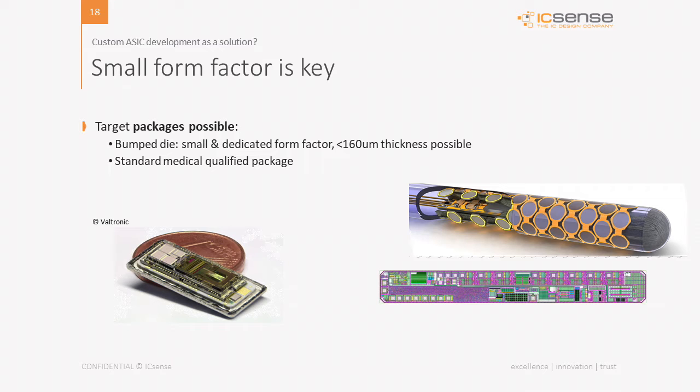On the other hand, we also see a lot of medical companies choosing standard medical qualified packages, such as a QFN and so on. The main reason is that in this case, you can use the same package for your whole product portfolio, also in between generations, and you don't have to duplicate the package qualification again. So it's a choice that you have to make as a customer. Is it the form factor integration, or do I want to standardize the qualification process within the company?